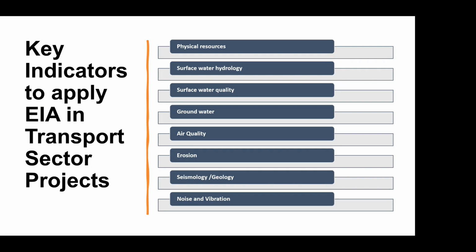The next part is erosion. The construction phase of a transportation project involves a great deal of earth-moving activity, such as cutting and filling, and borrowing different materials from stable areas. So there is a huge susceptibility to erosion of the top layer.